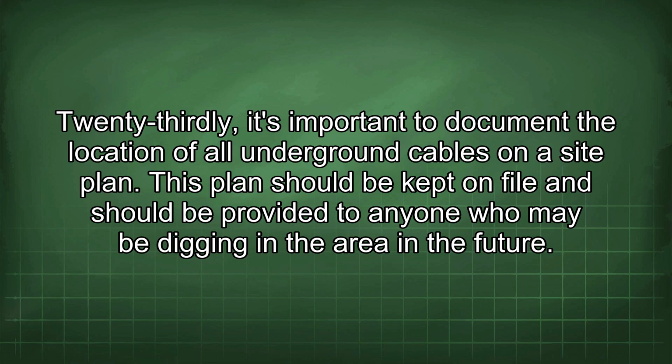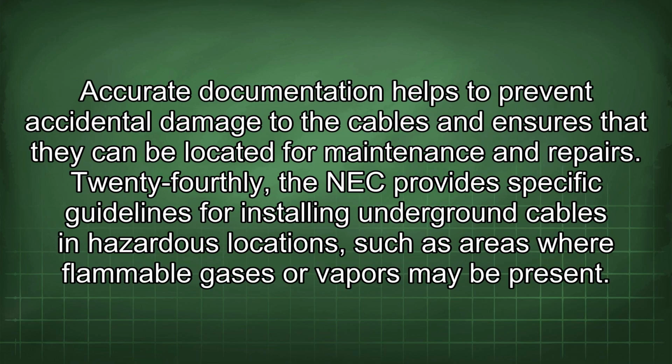23rdly, it's important to document the location of all underground cables on a site plan. This plan should be kept on file and should be provided to anyone who may be digging in the area in the future. Accurate documentation helps to prevent accidental damage to the cables and ensures that they can be located